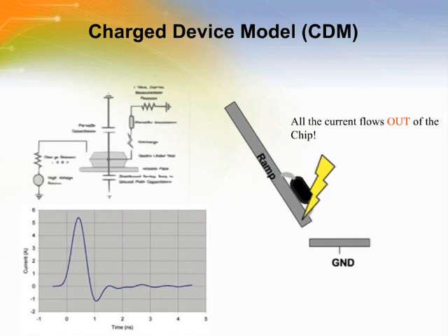This is a more challenging device to model and is based on the size and the capacitance of the IC being tested, with little impedance to reduce the current. This can result in high current, well above 5 to 6 amps, being discharged in a short duration of 1 nanosecond or less. Thus, this stands as the most practical real-world test for ESD issues today.